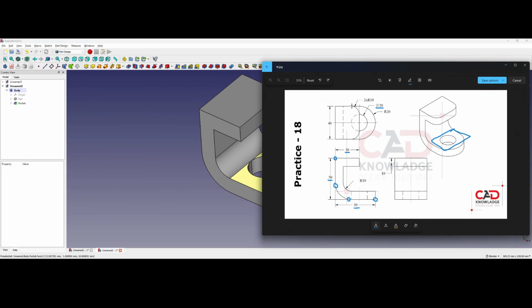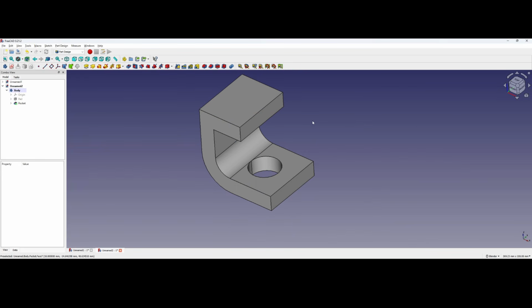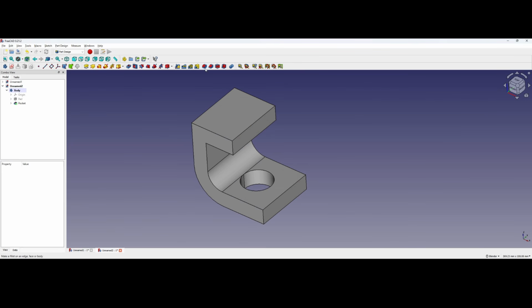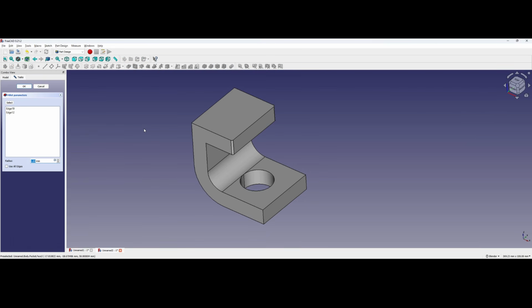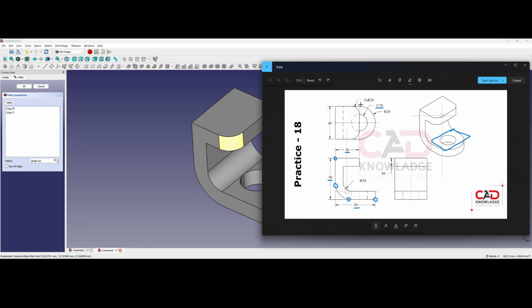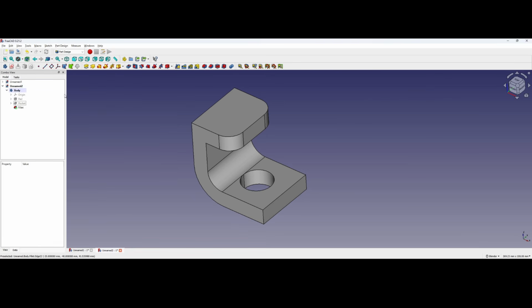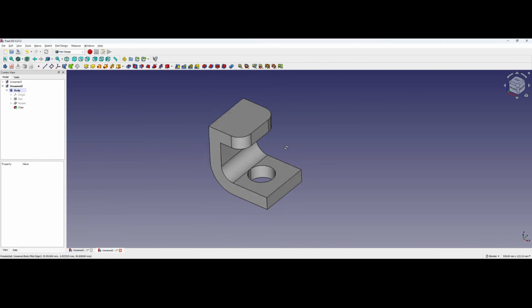So now I'll go ahead and create these rounded corners. Just like in the sketch tool, when we had the create fillets, we have a create fillet tool in the Part Design workbench. If you select these two edges here, and I was holding Control in order to select both of them, you can select fillet, and you can specify the radius of the fillet to create. Through our sketch, we know that this is a 10 millimeter radius. So click OK, and that's done.